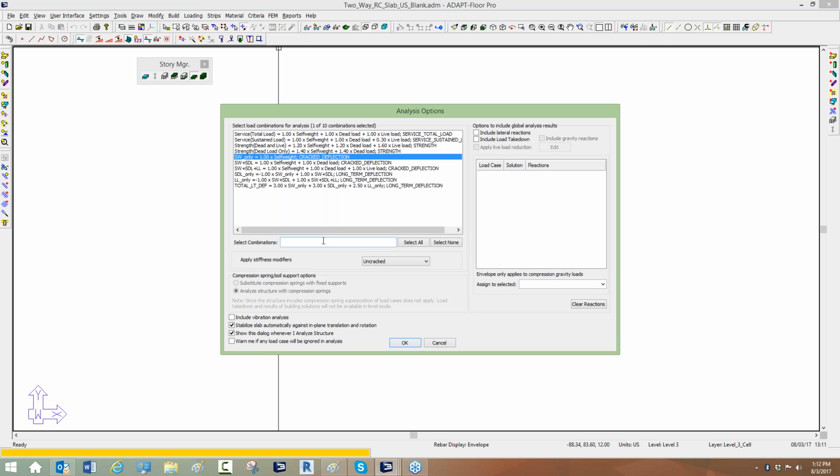So many times users might set up a modification usage case where they've already established a reduction in the slab stiffness for bending. And when they go ahead and run the crack deflection, the result can actually come out such that the general frame analysis reports a higher deflection than the cracked analysis.